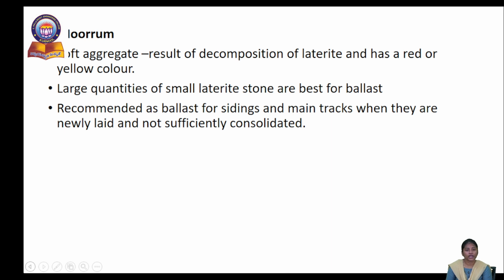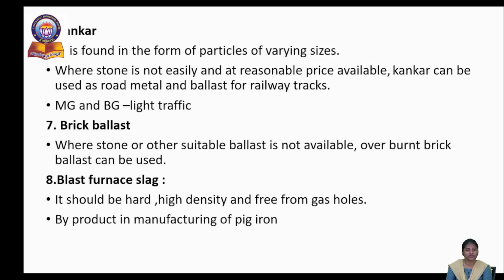Next is moram. It is a soft aggregate, a result of decomposition of laterite, and has a red and yellow color. Large quantities of small laterite stone are best for ballast material. It is recommended as ballast for sidings and main tracks when they are newly laid and not sufficiently consolidated.